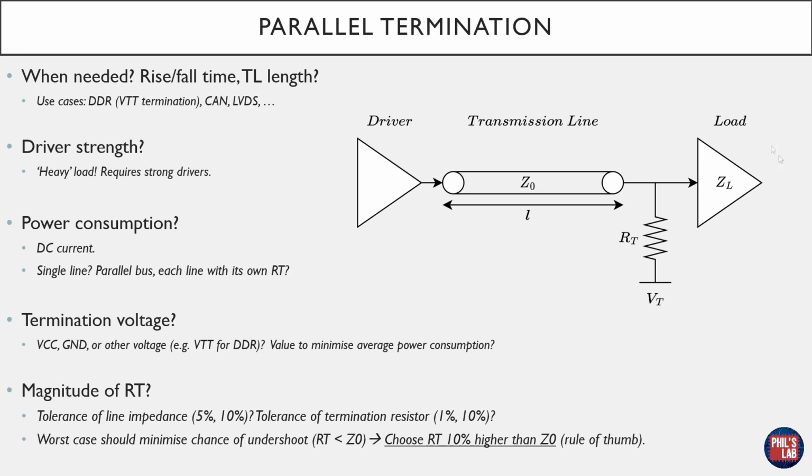This is because rather than now seeing a very high impedance load, this driver effectively just sees this termination resistor as a load. So for 3.3 volt logic and a 50 ohm termination resistor, that's quite a considerable current draw for typical drivers. So you need to make sure your driver can handle this.